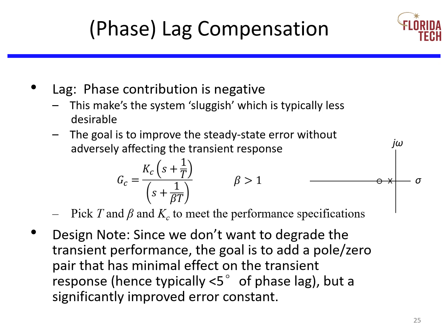For lag controllers, the angle contribution on the polar plot, also known as phase, is negative. Like lead controllers, we're going to add one pole and one zero along with the gain Kc. For lag controllers, the pole will be really close to the origin, similar to integral control, and the zero will be to the left of the pole on the real axis of the s-plane.